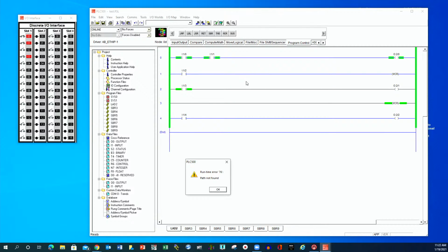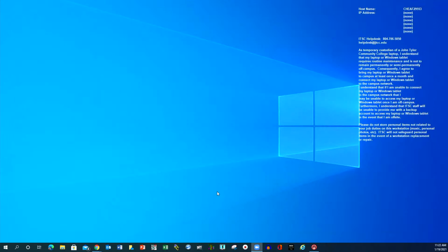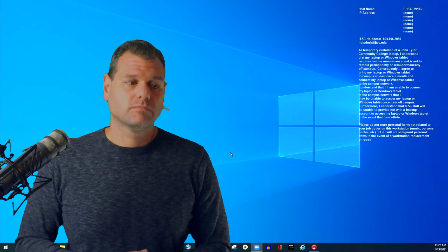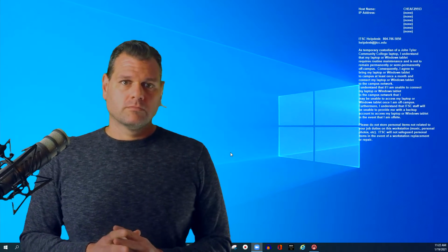So, I'll move on to the next after this one here. But basically, if it's within this fence, this line has to be true in order for whatever is between these two to be active. If I was to be able to turn on 1, 2, you would see the MCR come on, and then the output would instantly come on. If this is still true and the zone goes off, then you'll see the exact opposite. So Joe, the finish line for your master is always going to be on, irrespective of whether the zone is activated or not.